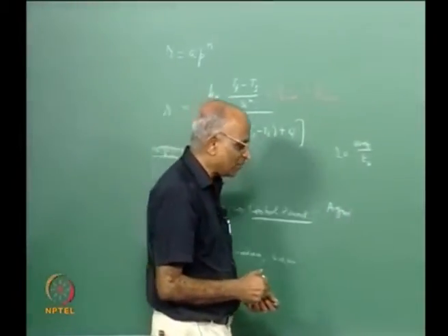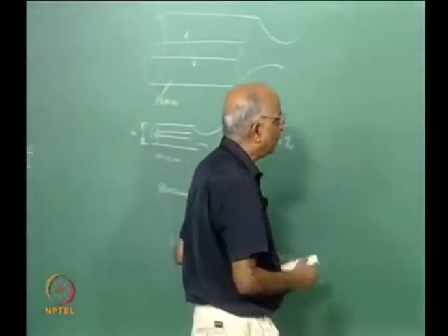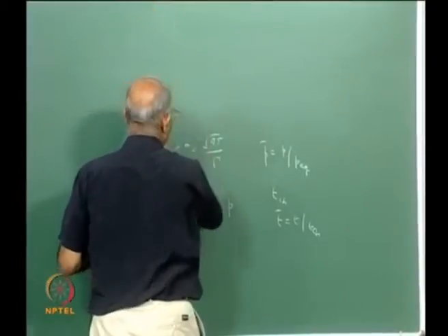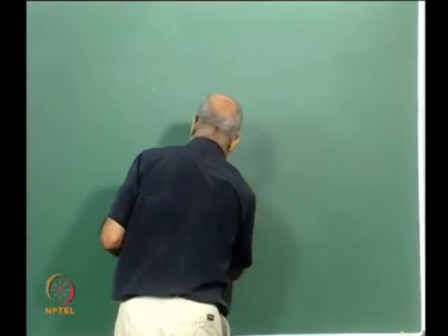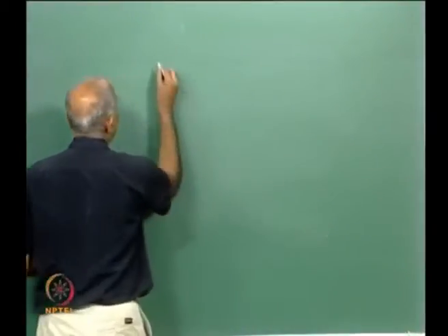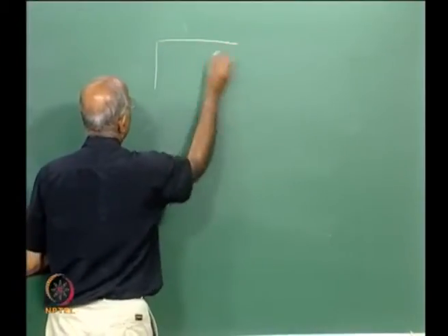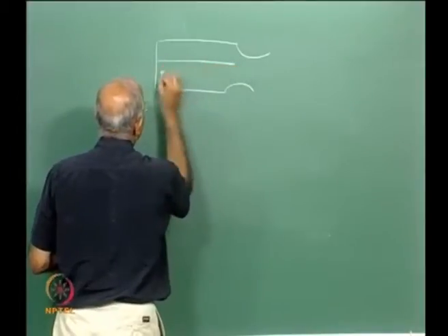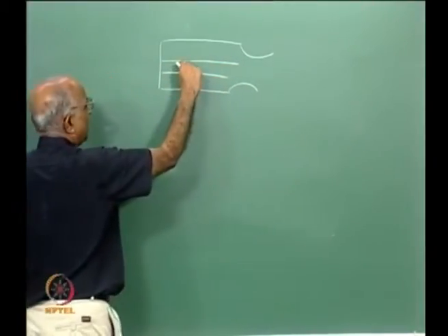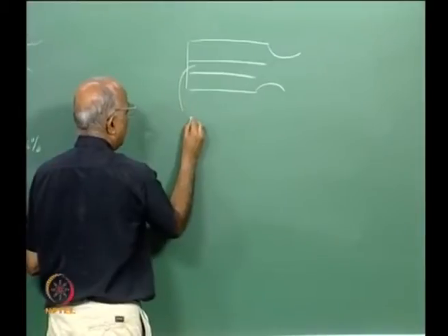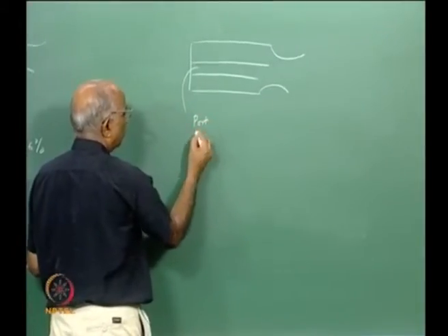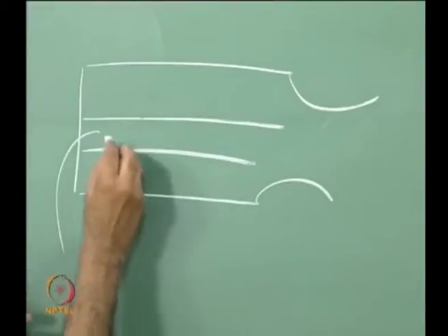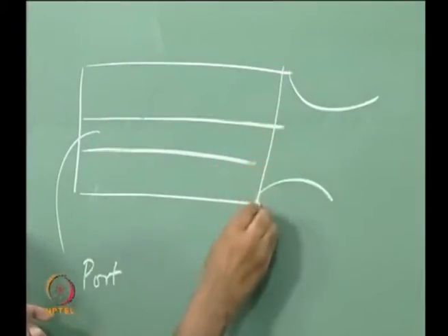This brings me to the last point, namely if we were to have a long propellant grain, let us say an internal burning grain, radial. The initial cavity diameter, which is also defined as the port of a rocket motor, that is the port cavity, is of small diameter and it burns at the surface.